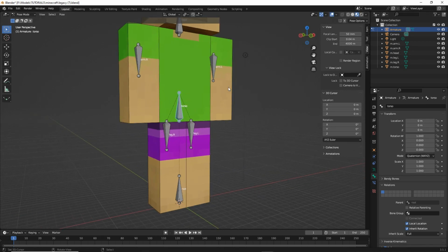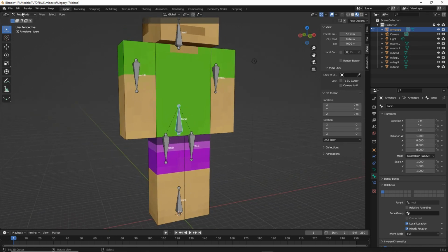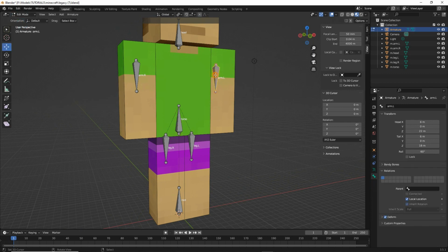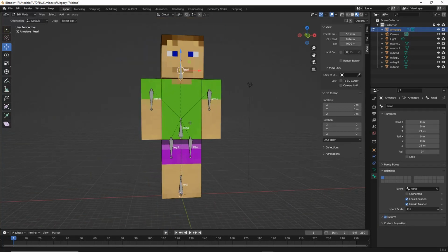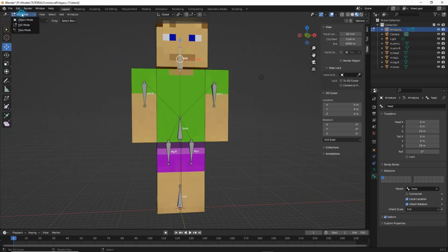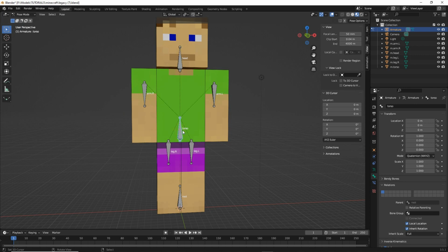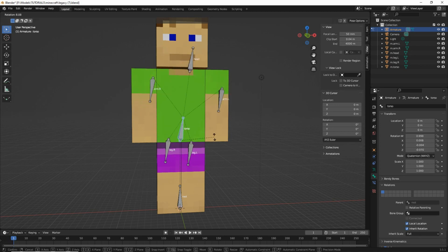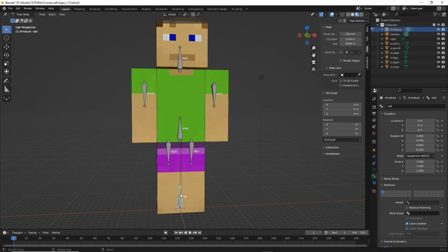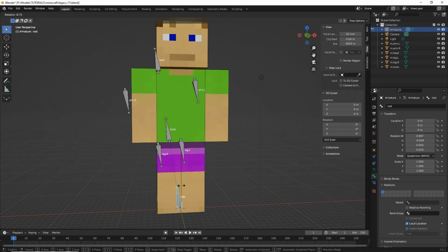What we're going to do is the same thing for all the other bones. Back into edit mode, arm, again from the list, torso, arm, torso, and then head, torso. So if we check the armature pose mode, what we have is selecting torso. That moves the character's main bones, representing each of the body parts, and then we have root that controls the entire armature.